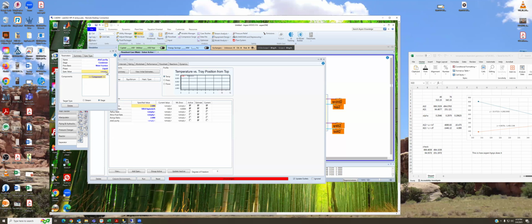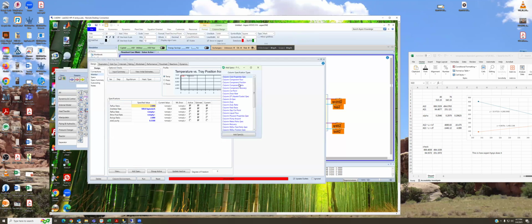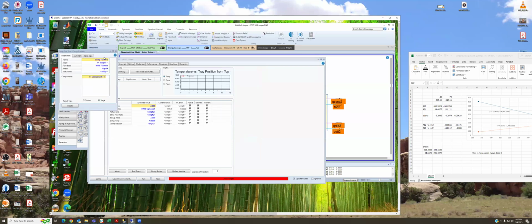And again, we said the top of this higher pressure column will be the azeotrope. That's at about 0.55 mole fraction of ethyl acetate. And finally, we'll add a bottom purity spec. We'll call this bottom 2 purity. Like that to the reboiler. And we should get pretty pure stuff out the bottom here. And this is where our ethyl acetate comes out.